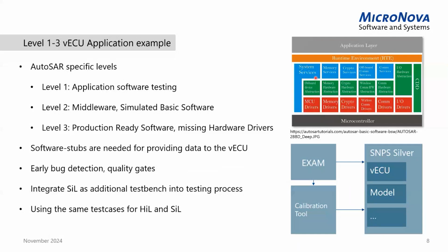And the setup that we might create out of this typically looks like this. We have a software product running the simulation of this virtual ECU, which might be Synopsys Silver for level 1 to 3, where we have a virtual ECU running alongside other virtual ECUs or models. We control this from the exam side. We might also employ some calibration tool here. And this setup we will also show a little bit later in the presentation. General advantages of this setup is that we definitely have early bug detection.